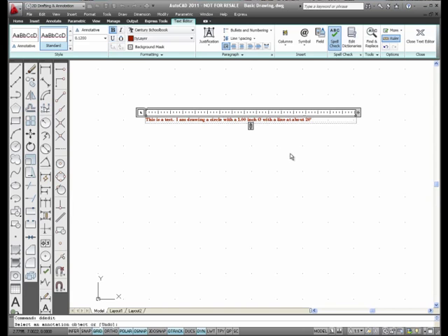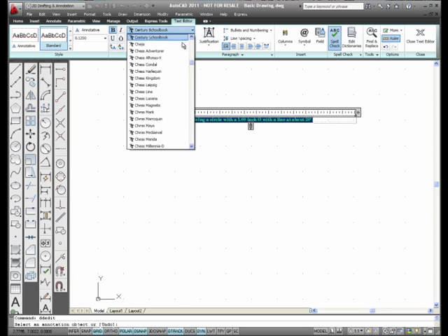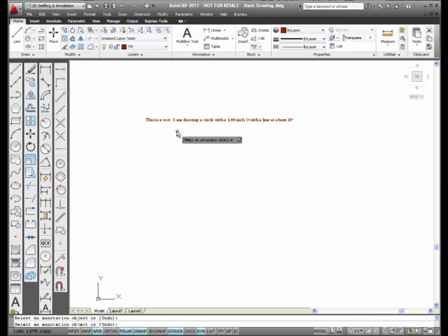at about 20 degrees. So you can get symbols for your text, and you can change it, remember, by sweeping across it, scrolling this down, and changing to whatever you want. I can even try Dutch. Click out, and I am done with it. And this is multi-line text.